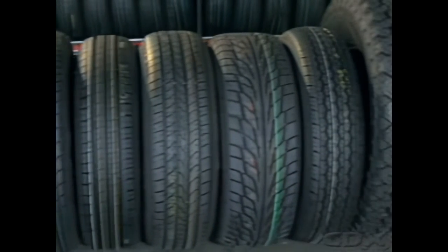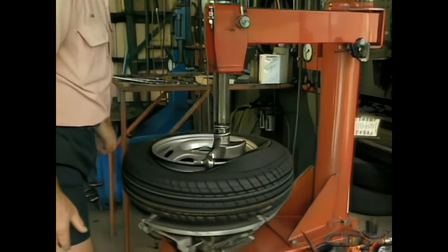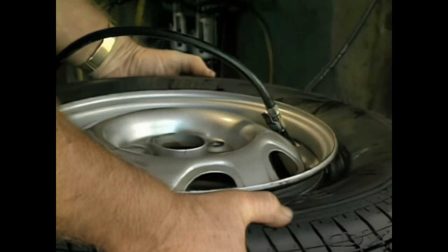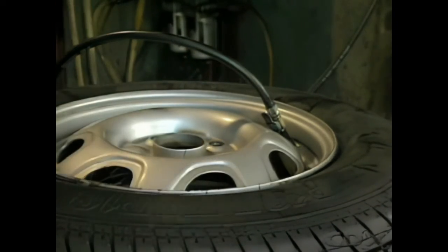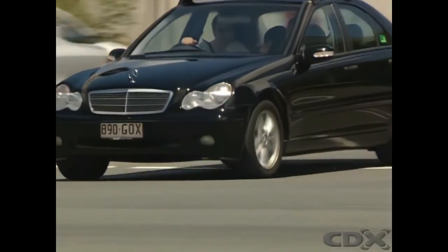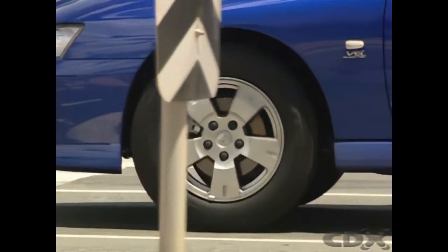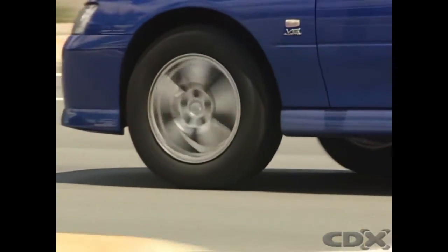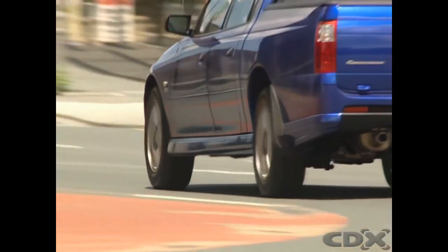The size of a tire must satisfy some basic conditions. The bead diameter must suit the wheel rim diameter. Section width must be suitable for use on the wheel rim and large enough to have a suitable load-carrying capacity for the vehicle. The overall tire size must allow sufficient clearance between the tire and the vehicle frame.